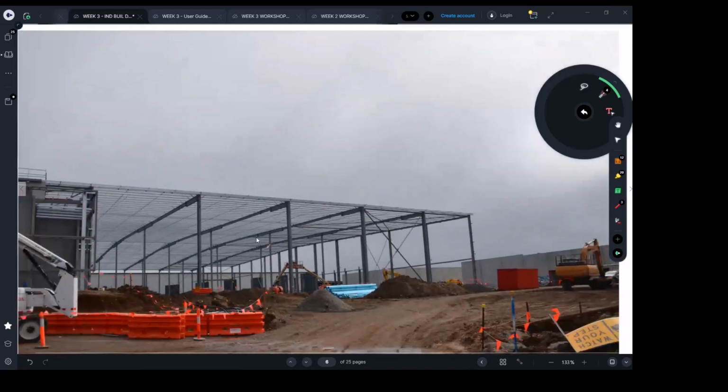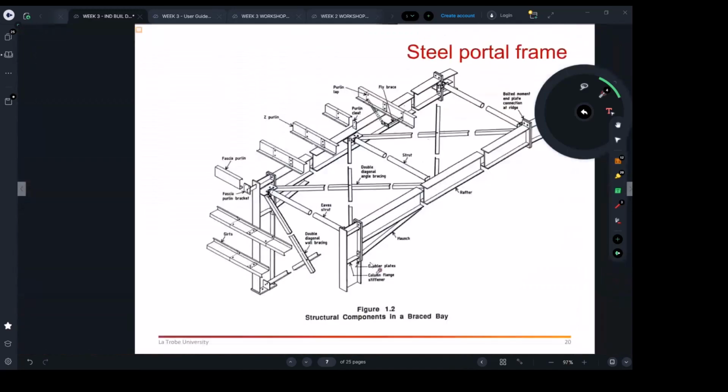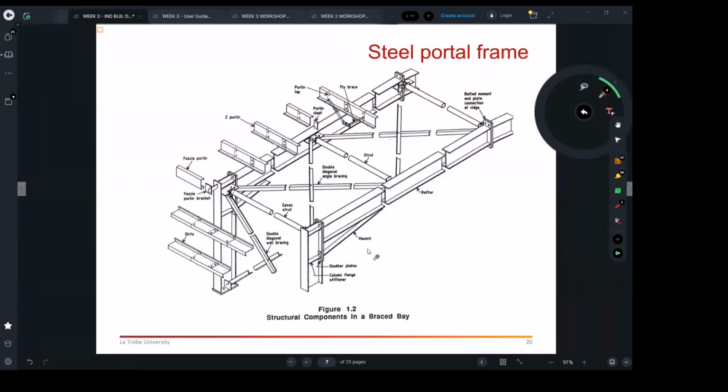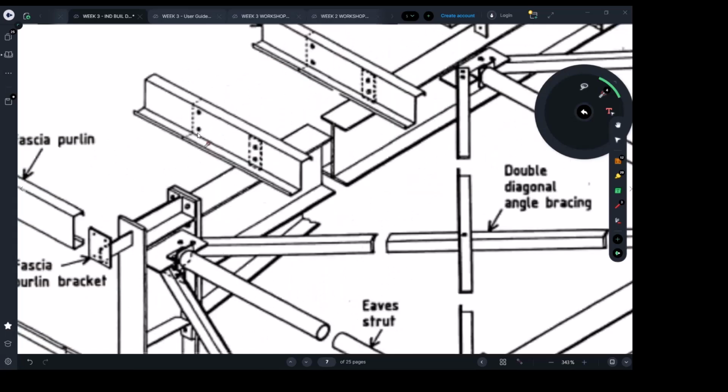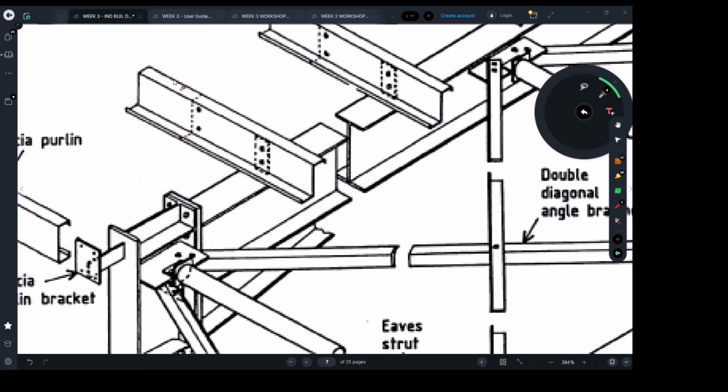So yeah, spend a few minutes to really see in reality how things look, and then you start building. I think this drawing is a continuation of the 3D image I showed you before, to help you understand more about the lapping I just mentioned. You can see the purlins or the girts are typically open channels. They're not like a rectangular hollow section or a circular hollow section like this.